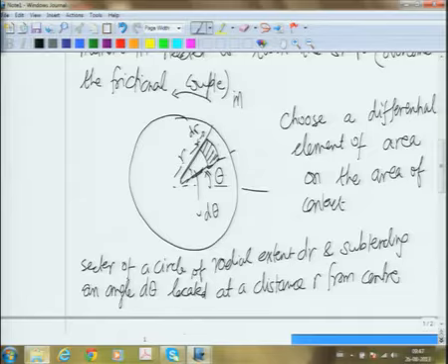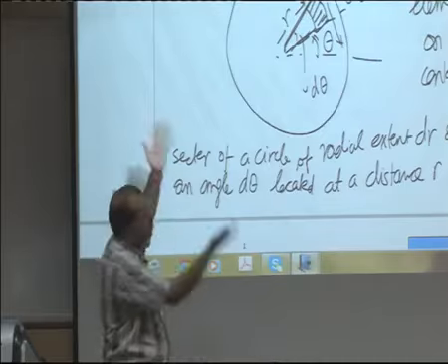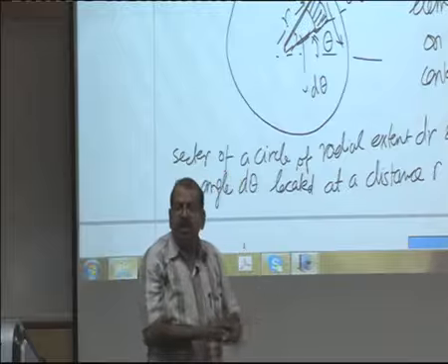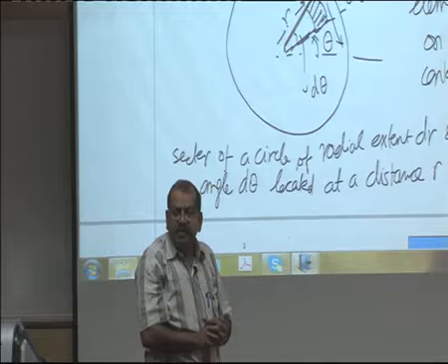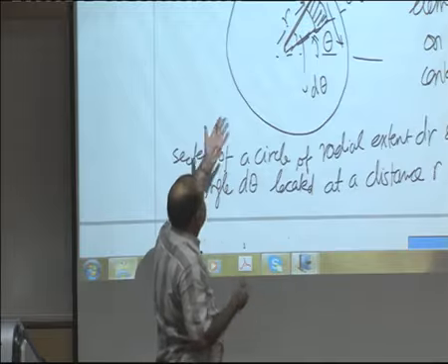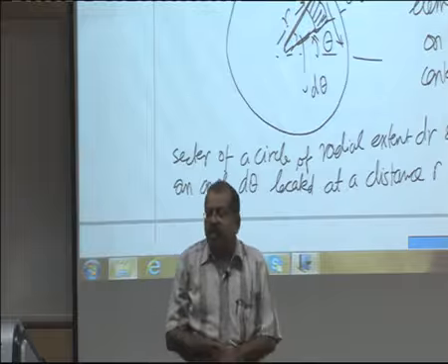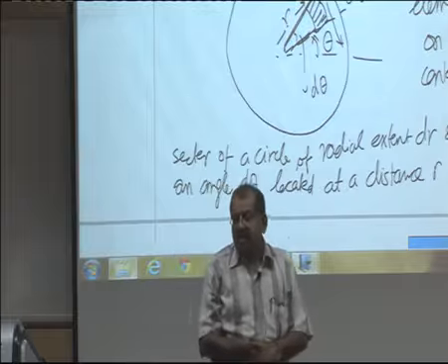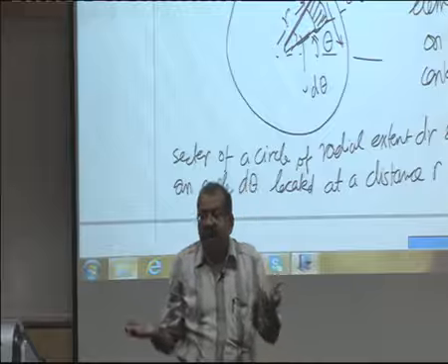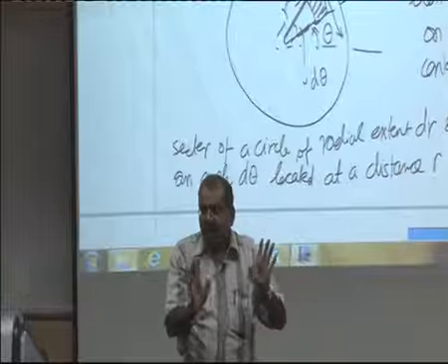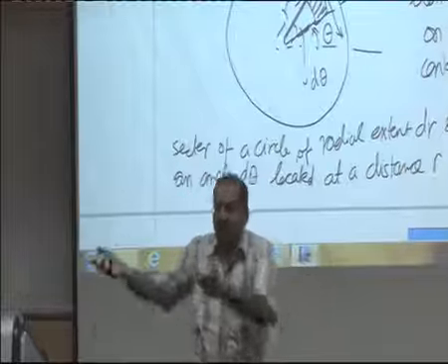So on this we will have a force of friction which I will call dF, because this is trying to rotate in the other direction. So friction force will try to oppose this. So this will be the direction of dF. Okay. Now what will be dF in terms of dn? It will be mu s dn when it is about to slip, otherwise it will be less than that. So we keep that in mind, dF will be just mu times dn.